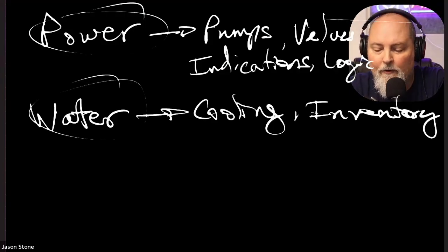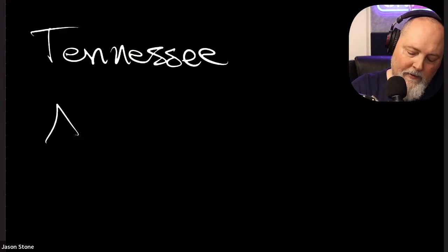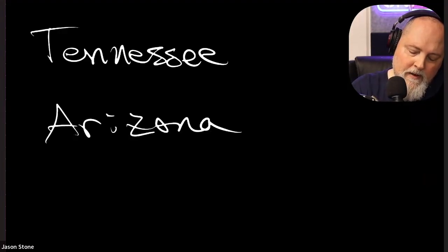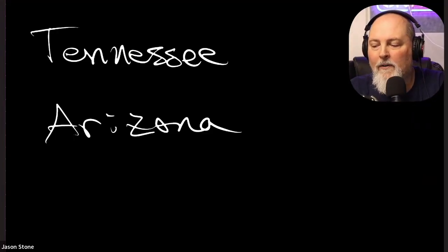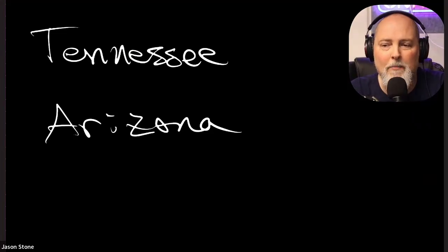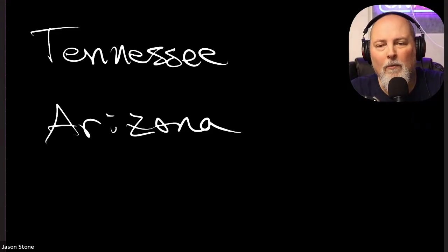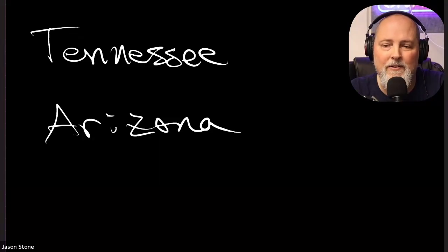So we have two centers called SAFER centers. One is in Tennessee and one is in Arizona. And they're big warehouses that house all of this portable equipment, pumps, generators, all that. And they have all the connections needed to hook up to the power plants too. In fact, most of the nuclear power plants, I think all, had to go through and make modifications to some of their systems so that we had common connections that matched the equipment they were using for the SAFER center.